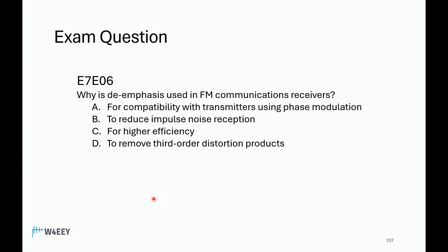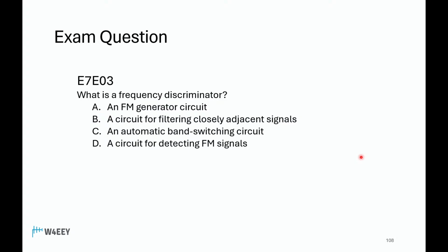Alpha. I think I heard alpha, for compatibility with transmitters using phase modulation. The reality is it's also for compatibility with direct FM that has been pre-emphasized. So it's really both cases, but this is a true statement, and it's the only one that is true of the ones that are given here.